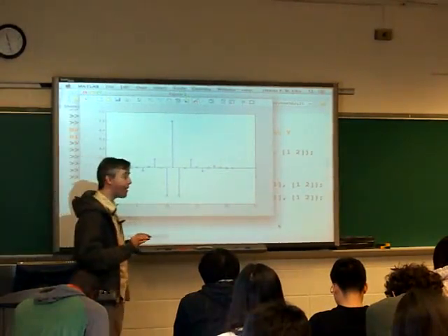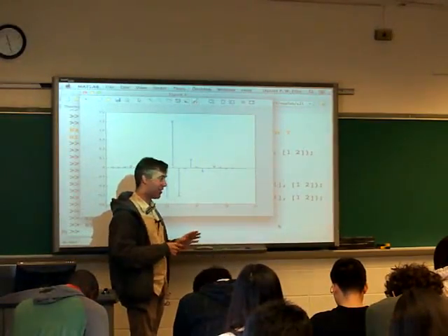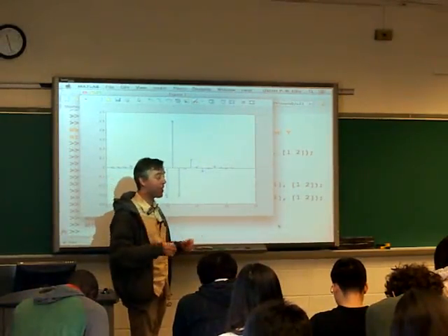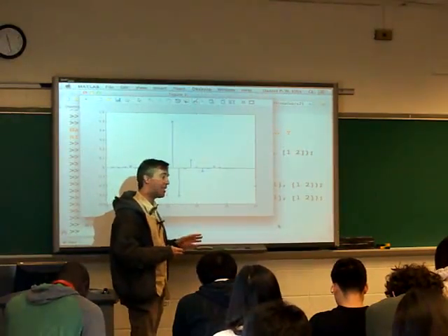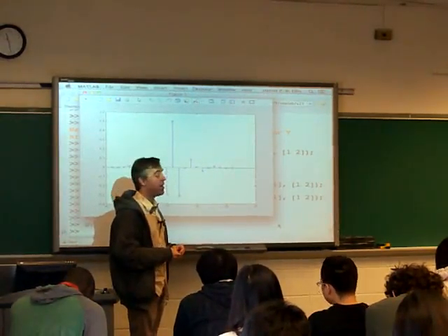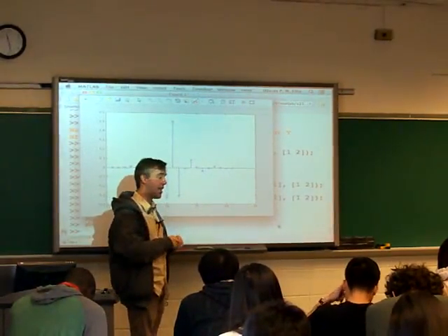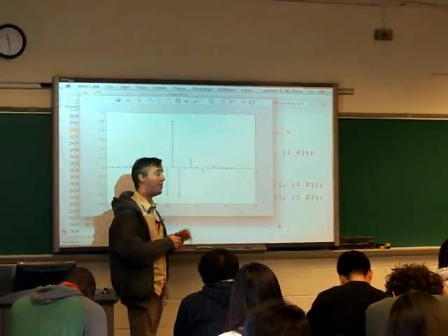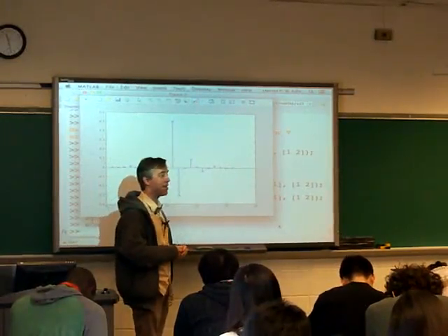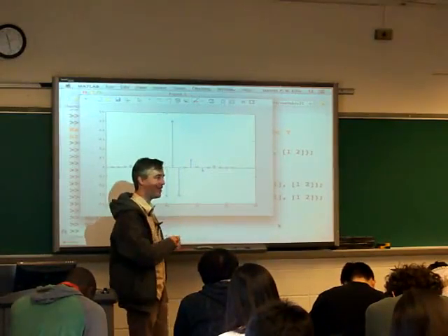Absolutely. So this filter is different from the windowed optimal impulse response, right? It's not at all the same, because the windowed optimal response had some ripples, but they were not equal depth. Now it's going to look pretty similar, right? Because the difference may be the difference between minus 20 dB and minus 30 dB or minus 40 dB. But what that means is slight variations of a few percent in those values. So they'll visually look similar, but a few percent difference down at minus 60 dB is a big deal. So it's just tuning those values a little bit to get exact cancellation in some bands.